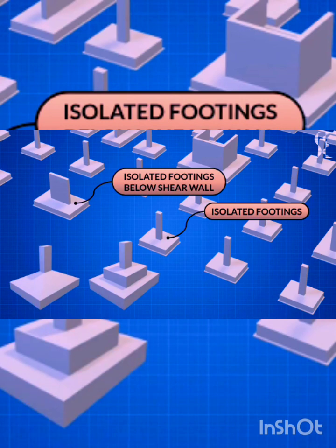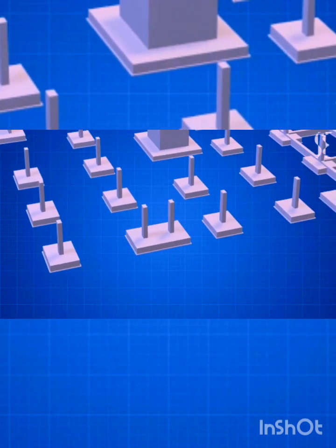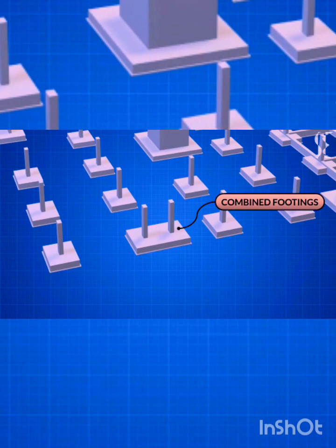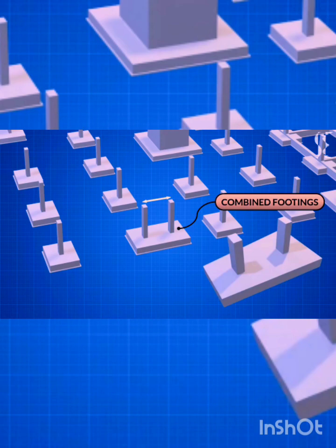Next comes combined footings, which accommodate more than one column. When the spacing of adjacent columns is so close that the separated isolated footings are not possible due to overlapping areas of foundations or inadequate clear space between two areas of the footings, combined footings are provided. Such footings are either rectangular or trapezoidal in plan with or without beam joining the two columns.